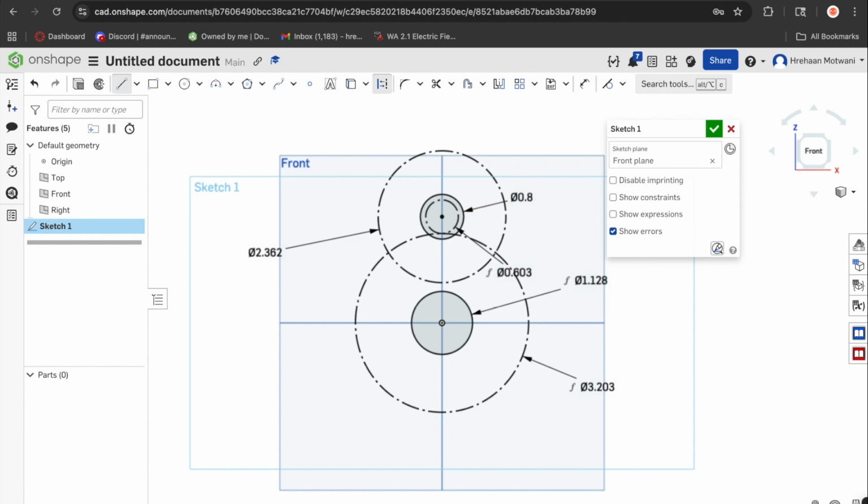And then the holes on a Kraken X60 are 1 inch from the center, and they are 10-32 holes. So you would make these 0.196 for 10-32, and then you would make it 1 inch from the center.